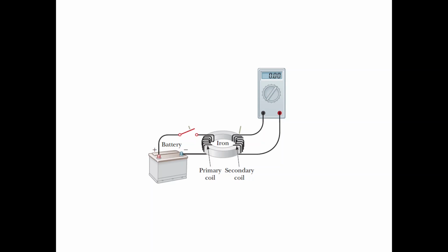Let's say it's on, it reaches some saturation, this current goes to maximum magnitude, which is defined by the resistance of this coil and the potential difference at the terminals of the battery. Then we have a stationary condition, nothing is changing. Magnetic field flux remains constant, and in that case we will not measure anything, because there is no magnetic field flux change over time, no induced electromotive force.